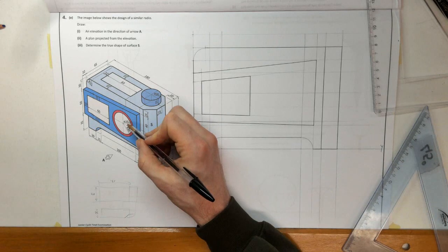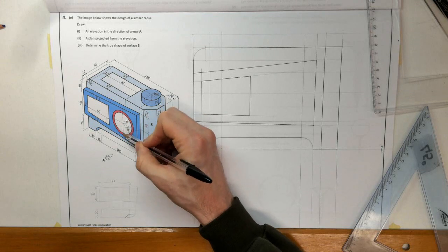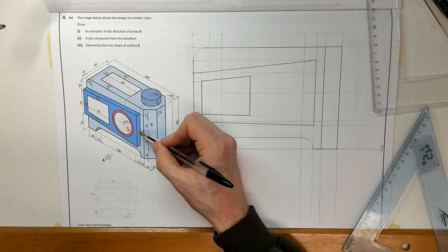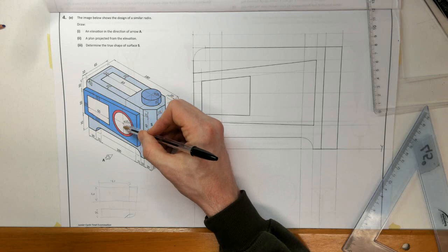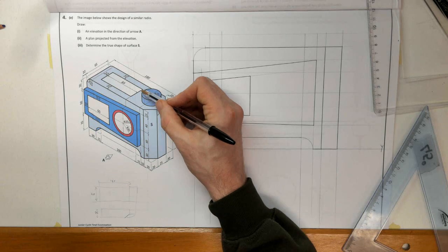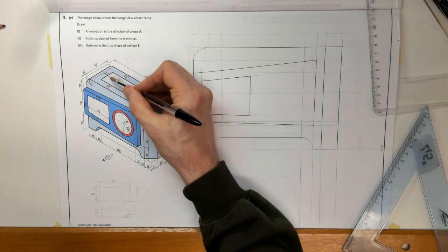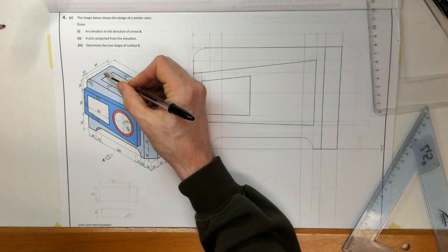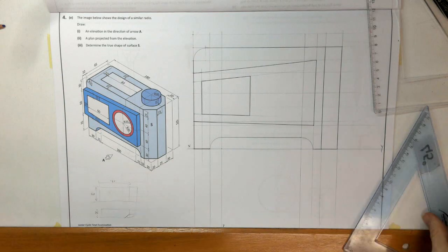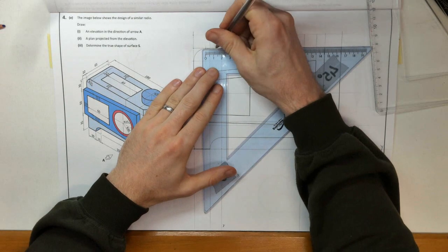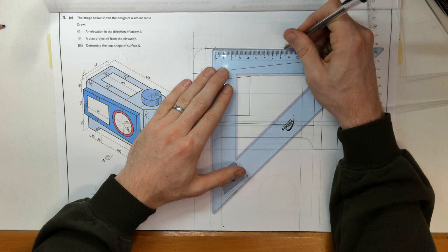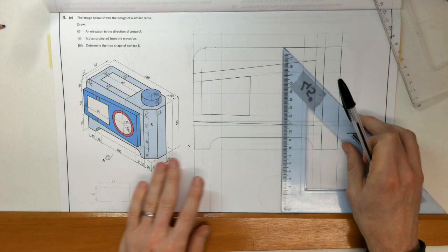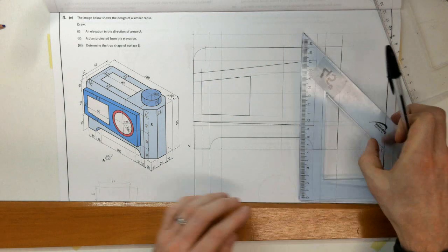So I have this circle that I need to find the center of. There's no measurements going this way to show me where it's going to be. So let's follow my guideline, that light line coming back up to here. We've got a distance of 82 and 12, and then I've got my curve. So that's the start of my curve. I'm going to measure my 12 from there, and then 82 from there, which is going to be 83 from there. So from that 83 mark, I'm just going to drop that line down.